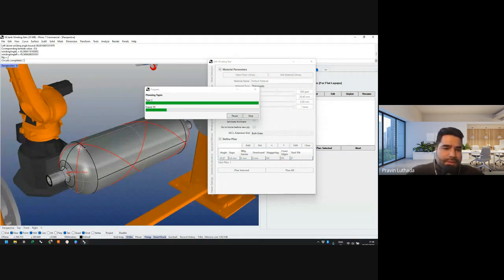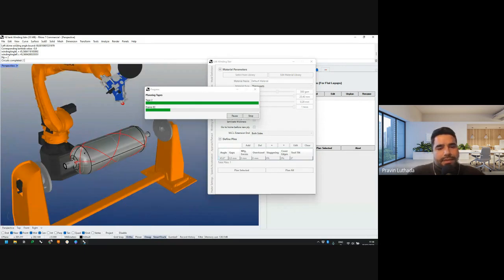So the frames are basically asking the robot to be perpendicular to the surface, and making sure that the robot aligns the tool's forward direction with the tape's forward direction. If you have these frames correctly planned, then your robot would come to that particular place and move in that direction. That basically ensures that you would have the placement of the tape in the right direction.